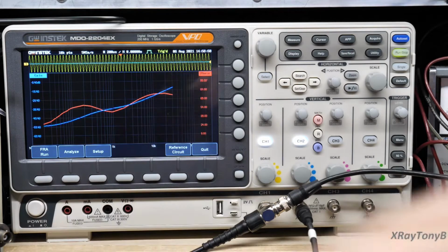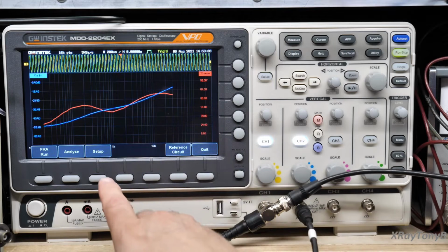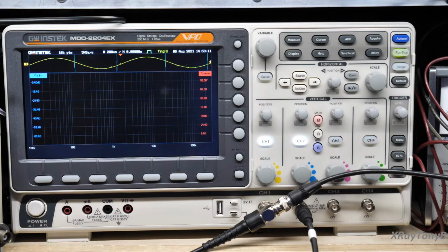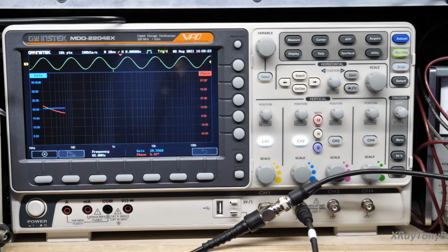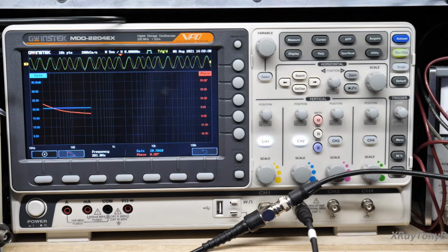And now we're going to turn the amplifier up. I'm going to run this to about 5 watts per channel into the dummy load. And we're going to run the frequency analysis. I have all the tone controls set flat right now. So we're actually looking at the signal going into the auxiliary input of the amplifier and coming out of the speaker terminals into the dummy load.